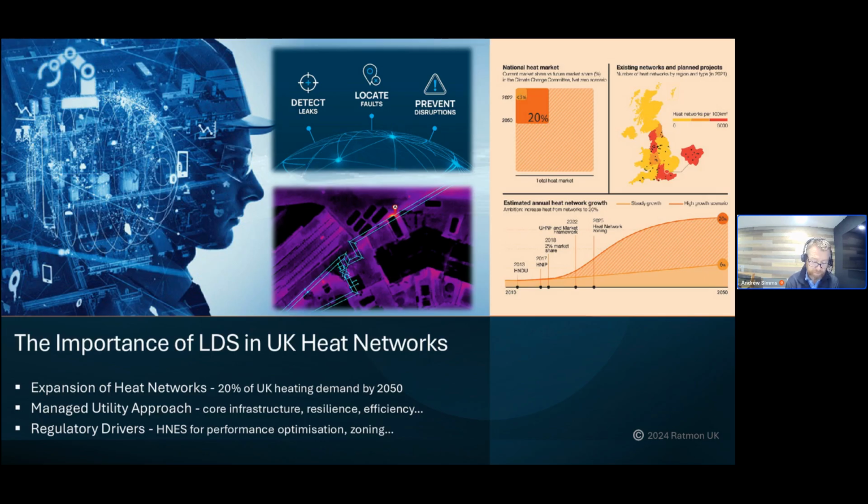Improving standards is pivotal to the growth, and there are documents to assist you, such as CP1 and the new set of technical standards that heat networks, both new and existing, will have to meet through an accreditation scheme. Owners of heat networks will need to bring existing heat networks up to a higher standard, and part of this will include that there are surveillance systems in place to monitor the buried pipes to avoid unnecessary leaks or outages, which could have been avoided.